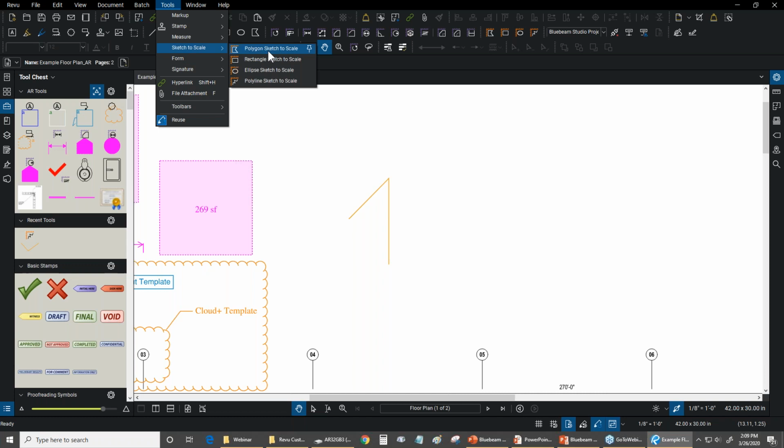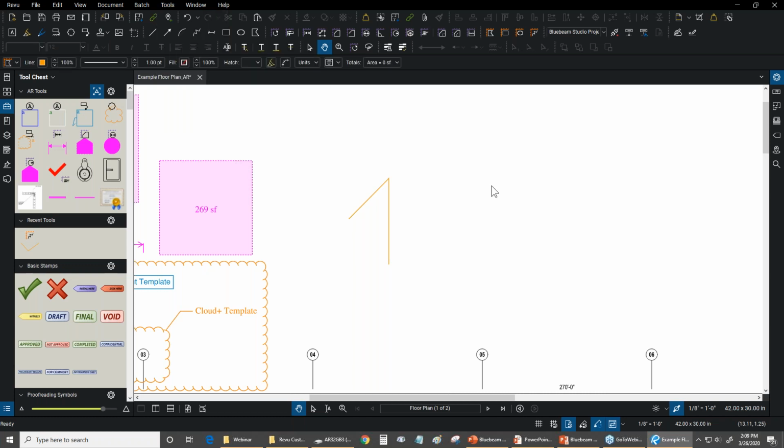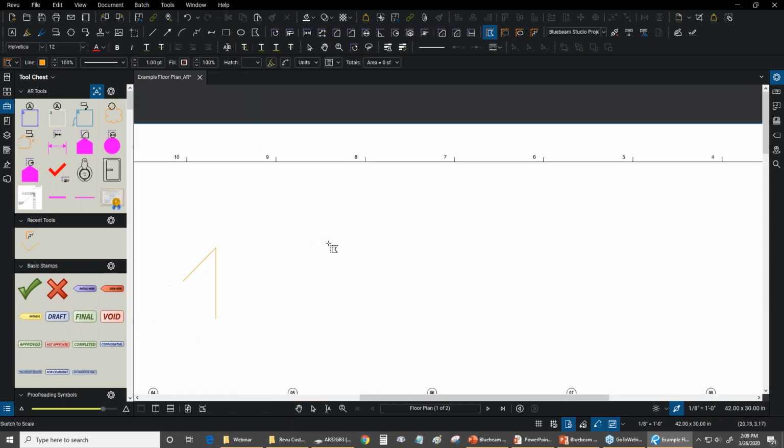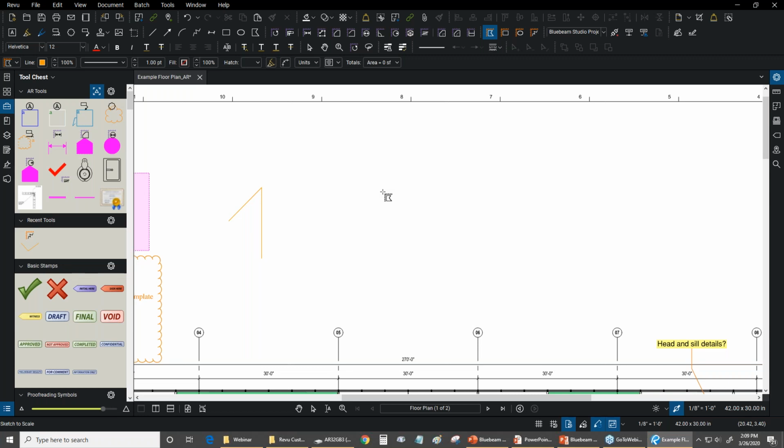Let's look at some others. We're going to look at the polygon one, and I'll show you guys how we can close a polygon rather quickly. Let's say that we wanted to make something similar. We want to make basically a triangle. So we're going to go at this origin. Let's go this time at -45 degrees. Oops, let's set our length first. That would be really useful. We'll press tab, -45. So now we're going down to the right.